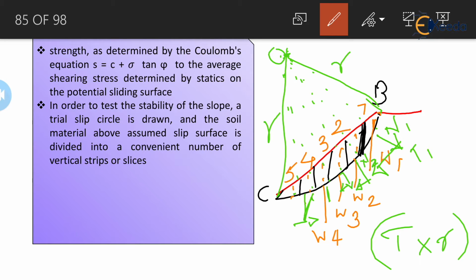Some of the tangential components are responsible for causing a driving moment, which can stretch out the slip surface of that given section, and this resisting moment will definitely protect that slip surface against the driving moment.